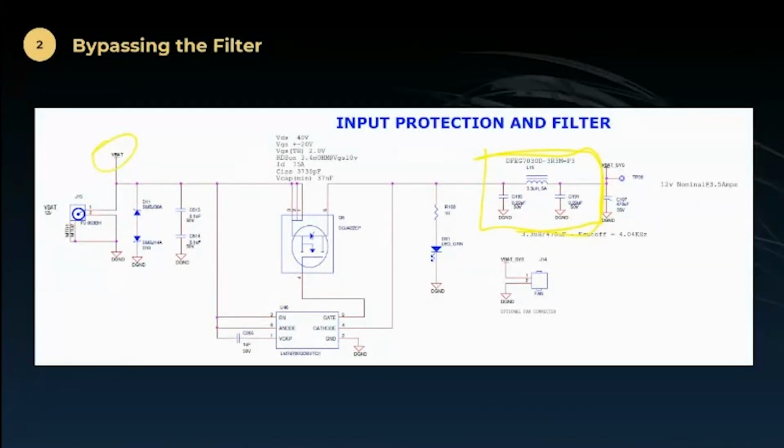So I colored every net on the board red or pink. And then I made the ground, the digital ground that we're referencing here, the D, G, and D, green. Then I went in and I found that net, made it yellow, that net, made it yellow, and then all these individual small nets in there. Basically, every net on one side of that, I just colored it yellow.